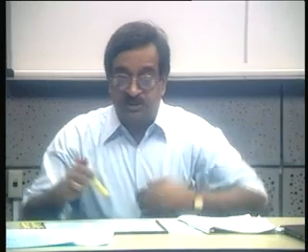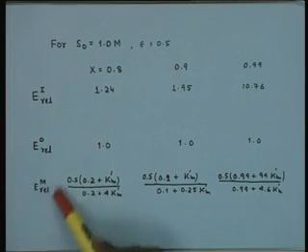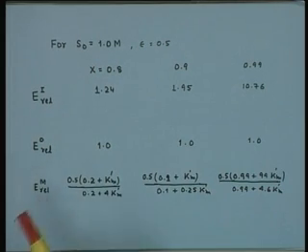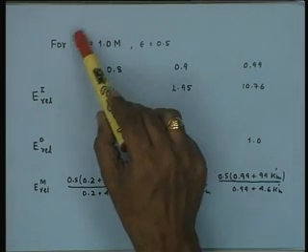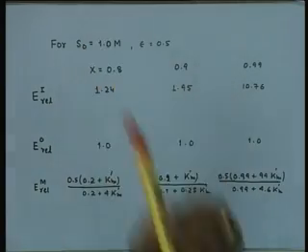In the case of zero order enzyme, there is no complication. Whatever the fractional conversion, the relative quantities required are identical, and so is the space time. On the other hand, in the case of Michaelis-Menten kinetics, when the Km and S0 are comparable, it will again vary, and it will be a function of Km. What is the magnitude of Km in comparison to substrate concentration? Here we have chosen 1 molar.